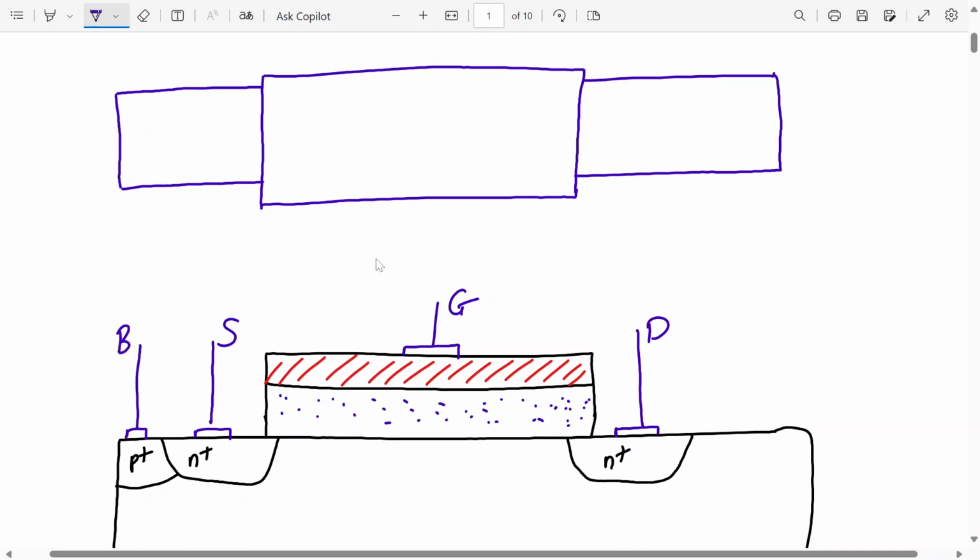Okay, now where is my source and drain? This is my source region from here to here. Alright, so let me mark it in green color. If I draw this dotted line over here, somewhere around here it will be my N plus source, and it will extend up till here. It goes inside the gate, overlaps slightly with the gate. Okay, this is N plus source. Similarly over here we have N plus drain, so it goes up till here.